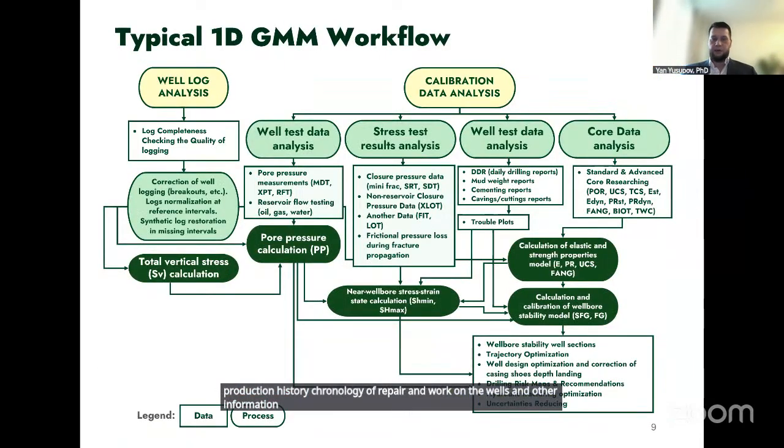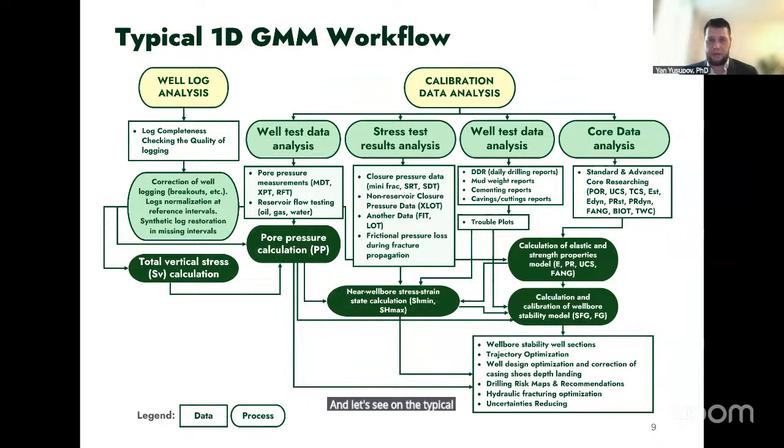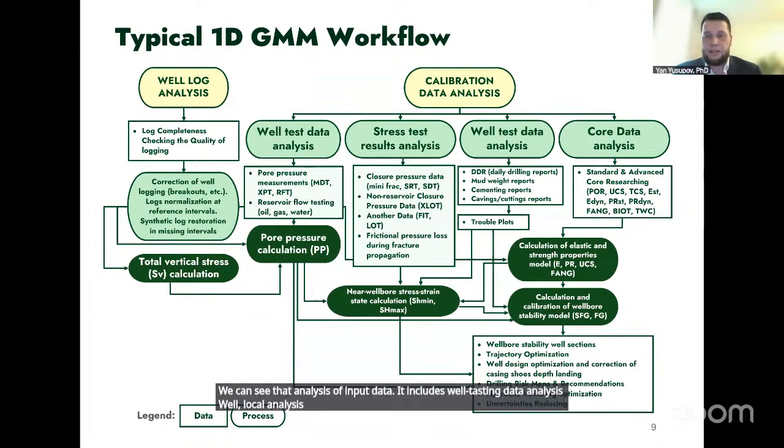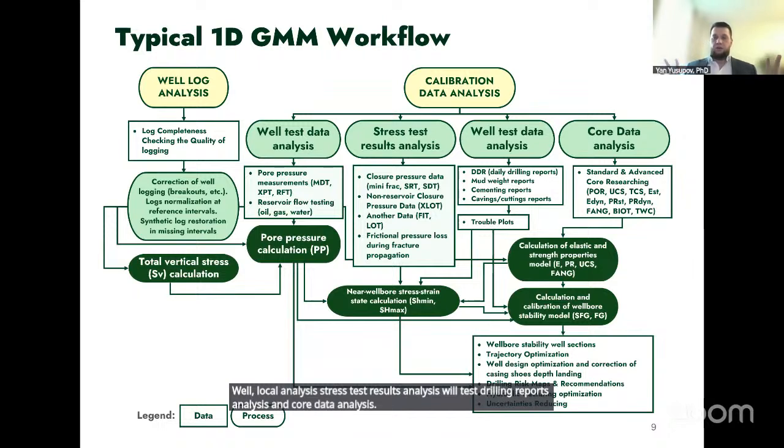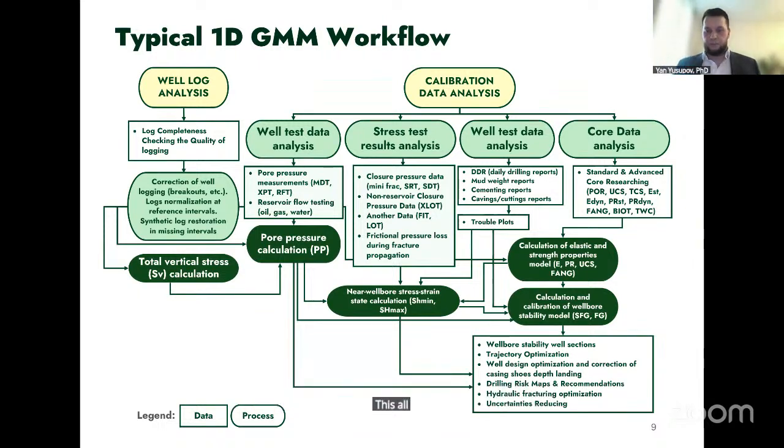Let's see the typical 1D geomechanical workflow. This is the workflow. At the head of this 1D geomechanical workflow, we can see the analysis of input data. It includes well testing data analysis, well log analysis, stress test results analysis, daily drilling reports analysis, and core data analysis. All this analysis leads to construction of the 1D geomechanical model.